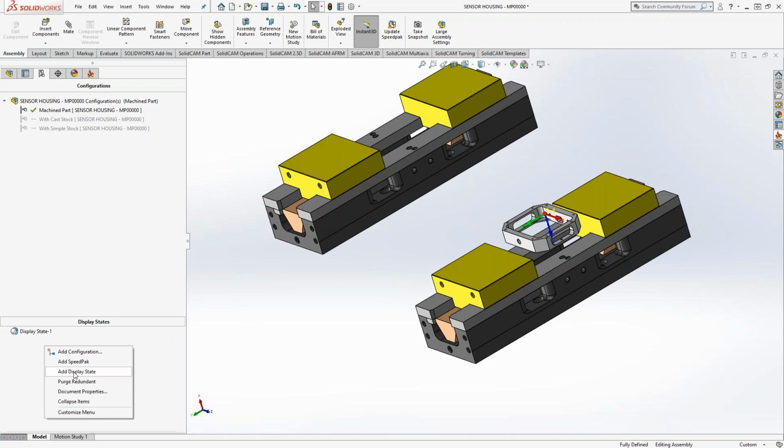Okay, last week. So what basically display states is I can add a display state by right-clicking and saying add display state. I'll call this one side 2, and I'll relabel the first one. I think double click on it. You may have to, it's just like configurations. Yeah, maybe just hit F2 on the keyboard. There it is. Okay. Side 1.